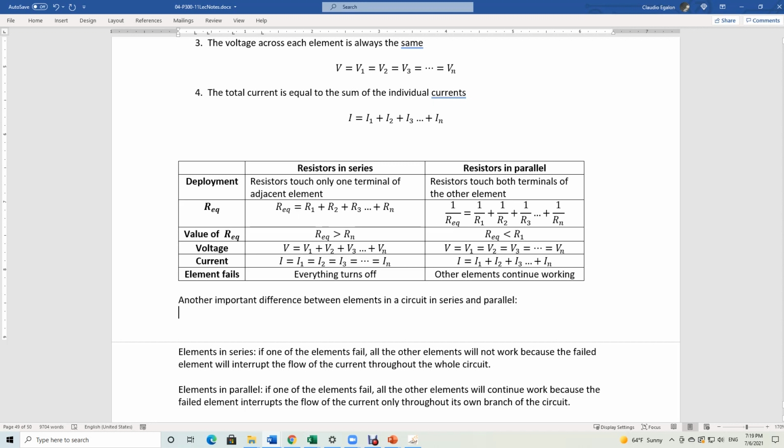Think about that Christmas tree. A Christmas tree doesn't have only 2 LEDs. It has a bunch of LEDs, 100 LEDs on it. Suppose that someone decided to connect the LEDs in series in a Christmas tree. If one light bulb fails, everything else would not light up, and you'd be checking among 100 LEDs which one failed. It would be a huge amount of work. Because of that, manufacturers of Christmas trees connect all the LEDs in parallel. So if a single LED fails, everything else works, and you can pinpoint which one is not working. Make sense? Okay.